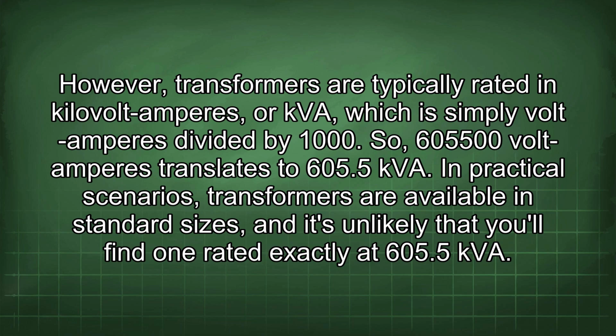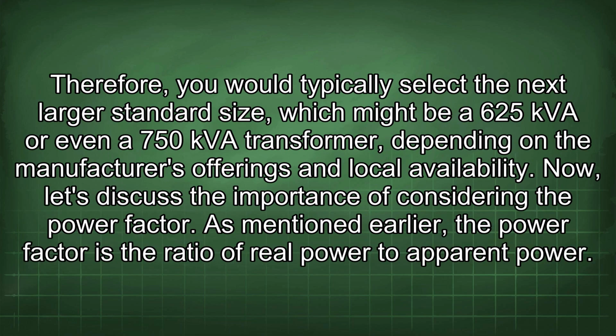In practical scenarios, transformers are available in standard sizes, and it's unlikely that you'll find one rated exactly at 605.5 kVA. Therefore, you would typically select the next largest standard size, which might be a 625 kVA or even 750 kVA transformer, depending on the manufacturer's offerings and local availability.